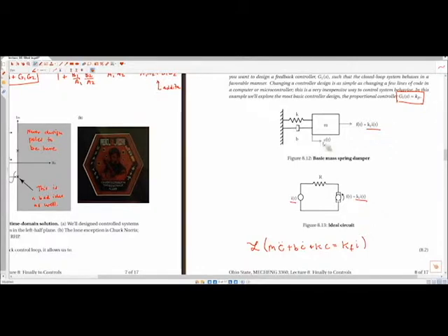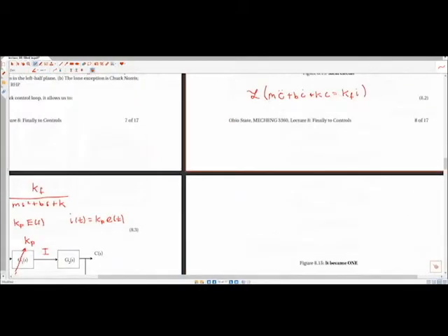That means in our standard equation for feedback, we're saying that the input, U of T, should be some sort of scaling of our error signal. Just a reminder from Wednesday, the error signal is the difference between the reference, which is our desired output, and the actual measured output. If this is a robotic system, this is the desired position and the actual measured position. So the error is a metric of how well we're doing. Is the robot arm where we want it to be, or is it a little bit off? That's the idea.